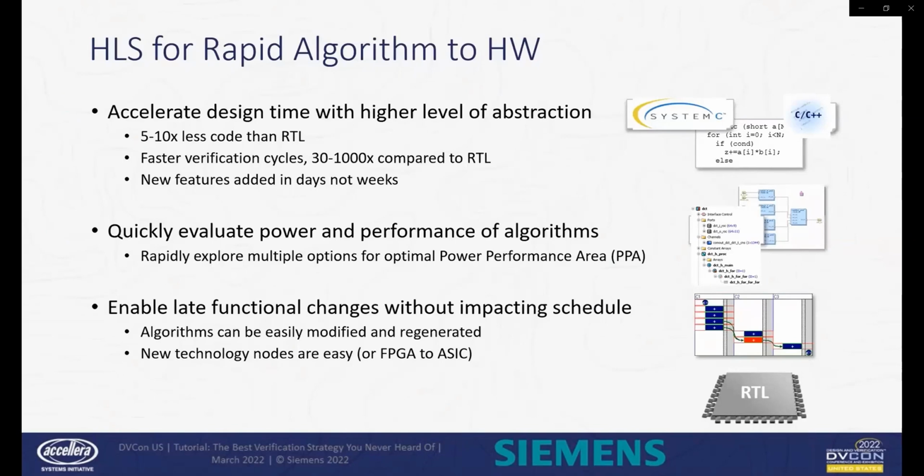And as a former RTL designer, I cringe a bit knowing how HLS facilitates late changing specifications, yet it is the case. More relevant, moving to new target technology nodes is easy, say as blocks get reused in next-gen products, or even to facilitate prototyping the same design on an FPGA prior to mass production via an ASIC.